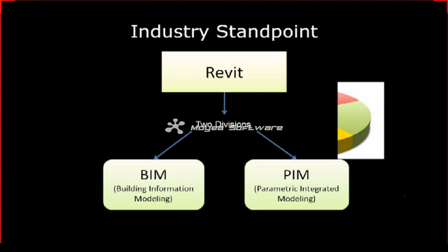Yeah, and BIM, just to give a quick definition, because there's like a million different definitions of BIM. You just Google it and you'll find plenty of different explanations of what BIM is. But essentially BIM is just adding that information level to your models, and that's Revit's strong point, the information side, but it's not just Revit, there's other programs as well. You have your ArchiCAD and your Bentley. But what these do is add that information to where it's not just a wall, it's actually a wall with properties to it. It has different layers to it. It has the way it interacts with other elements.